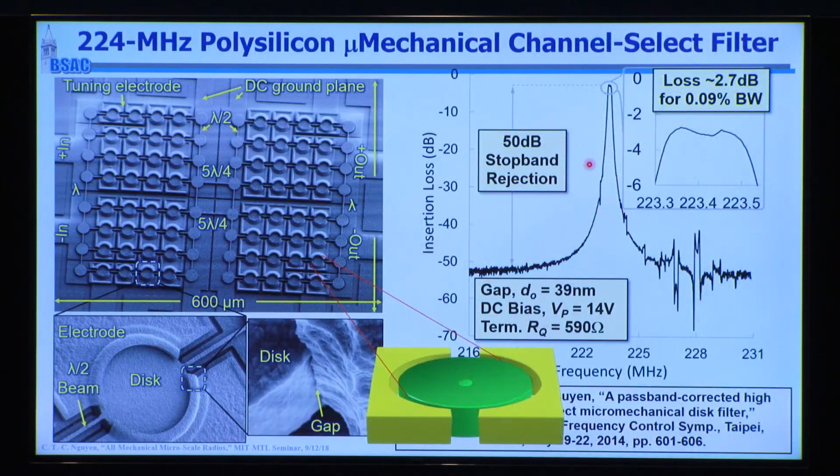And so once you create a resonator like that, if you have a good enough resonator, and so now these are different types of resonators. That was a ring resonator. This is now a disc resonator that has a mode shape like this, where it's still expanding and contracting around its circumference here, a breathing mode shape. But you can now take these resonators and you can make big circuits out of them. And when you make big circuits out of them, that's one solution to this impedance problem.